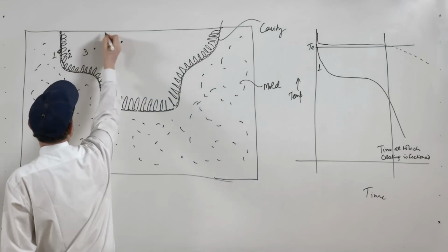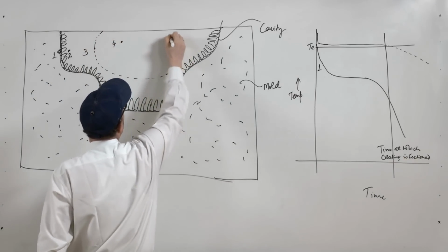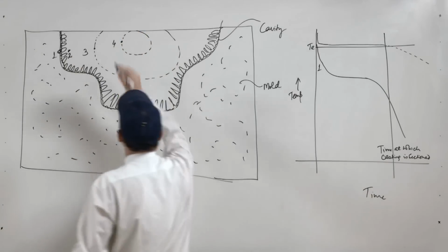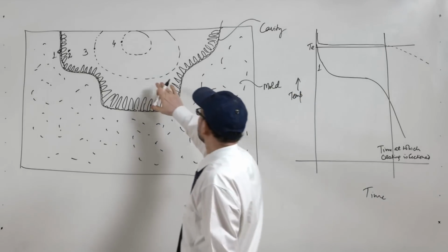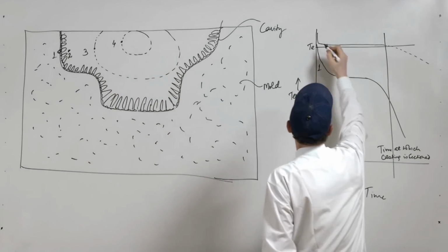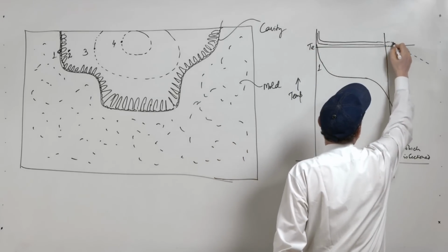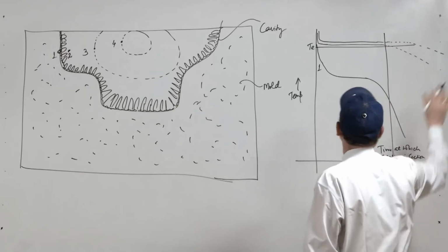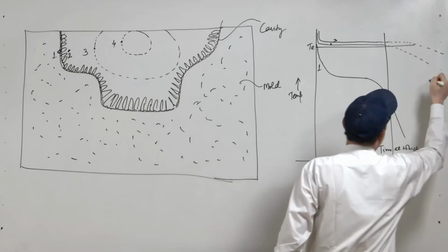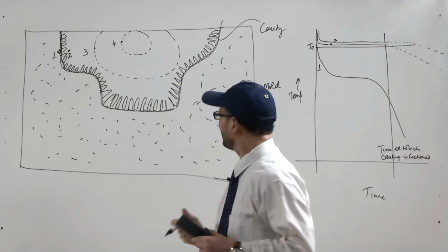Now, at this point, if you look at these cooling curves, the isotemperature curves will be like this. Similarly, on 4 it will be like this. So these are the isotemperature lines, they show where the temperature is higher. For this it will be further, and you expect that in future they will cross over this equilibrium temperature line, when the nucleation will take place.